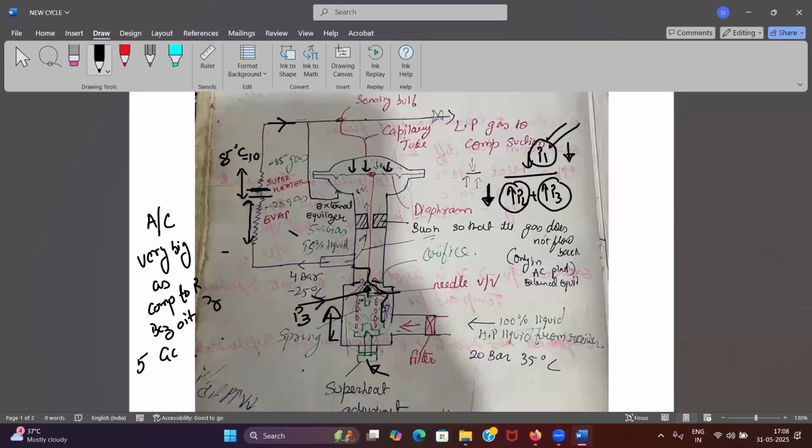So this temperature, what difference I was getting before, 5 degrees, now it will be more. Agreed? And because of this more degree, I will be having more pressure, because I need more pressure. I told you P1 should be greater than P2 plus P3. If you have increased P3, obviously you will be needing more P1 in order to open the valve. So you understood how the degree of superheat is getting changed by adjusting the spring tension.